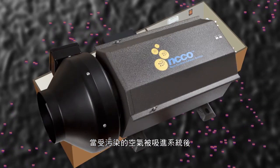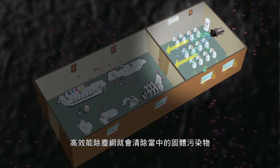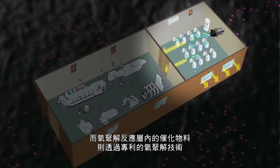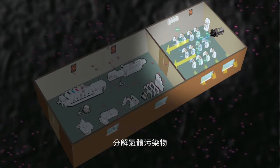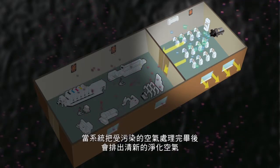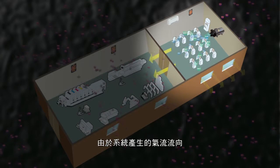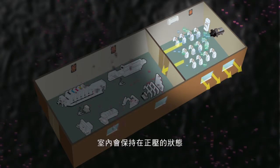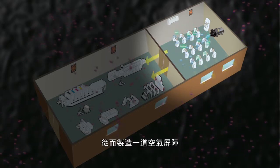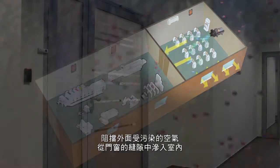When untreated air is drawn into the system, the dust filter will remove solid phase pollutants from the incoming air. Gas phase pollutants will be treated by the catalytic materials inside the NCCO reactor using our patented NCCO technology. After the treatment, clean and purified air is released into the room. Due to the direction of airflow created by the system, the room is kept under a positive pressure. An air screen is created by the system against the outside contaminated air, which is prevented from seeping into the room through door and window gaps.